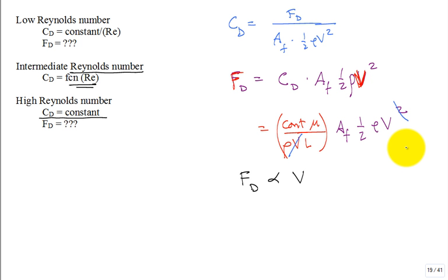Think about the Moody diagram. Was there any region where it was Reynolds number independent? There was. It's where the friction factor went flat as a function of Reynolds number. What did they call that in internal flow and pipe flow? They called it the what region? Completely turbulent, fully turbulent, some terms like that, different authors, different names. But the friction factor was no longer a function of the Reynolds number. You have the same behavior here for external flow. You can get that the drag coefficient becomes a constant, and this is very common in external flow. This other case is less common; this one is more common.